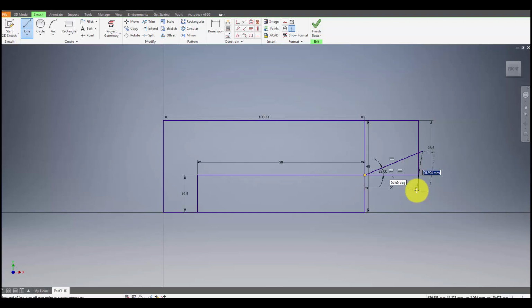It then asks you to draw a 12 by 12 rectangle from this junction, so just press escape, select the rectangle tool, exactly where they cross, click once, and then we can press 12, tab, 12, enter, and that is that square drawn to the correct size. Draw a line to the top rectangle, 29mm rectangle, and the 12mm rectangle. So click on the line tool and we simply join that one up from there to there.